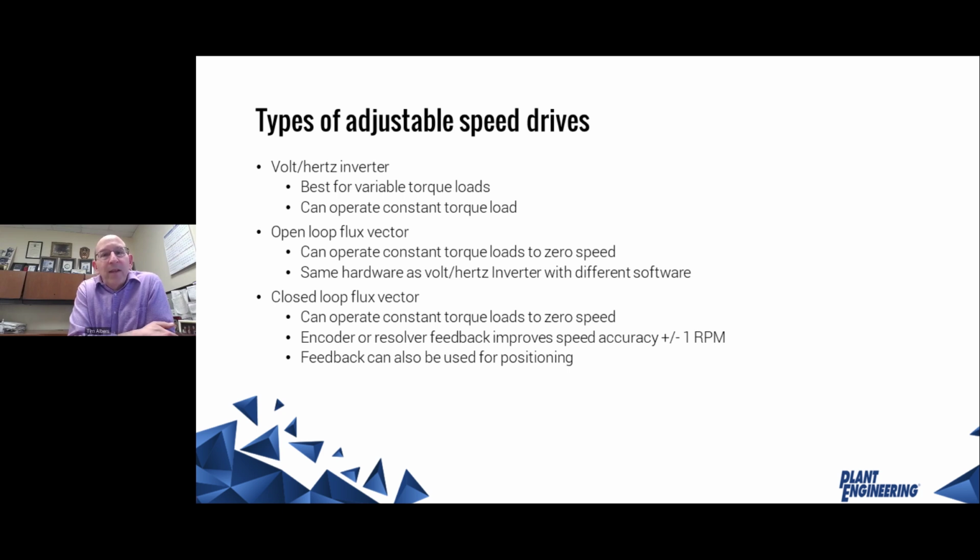Some of them, the hardware is the same between a volts per hertz drive and a vector drive. In some cases, it's not. My point is all of these will work for a power drive system, and particularly if you're doing a variable torque load, all of these will work. They just may vary in expense and maybe a little bit in complexity for setup.